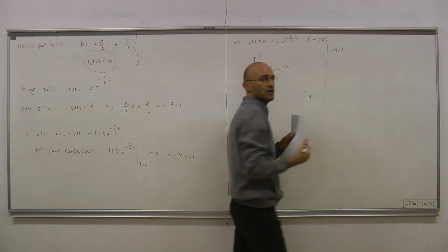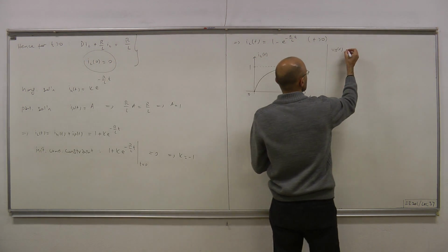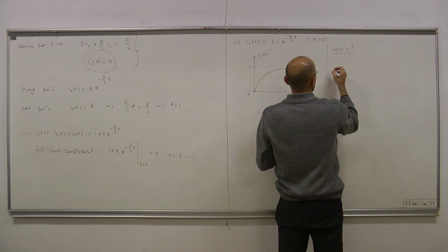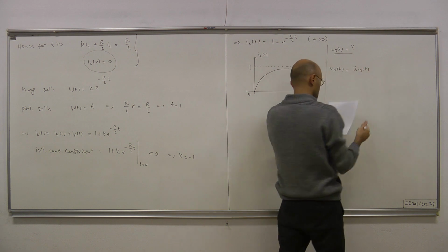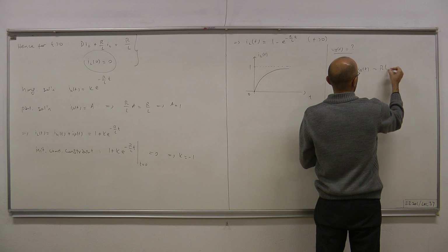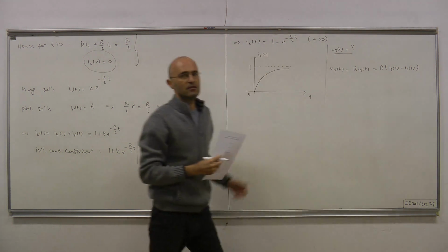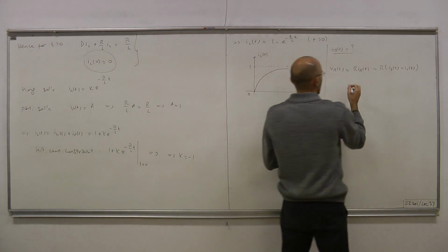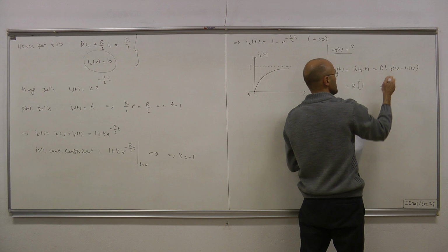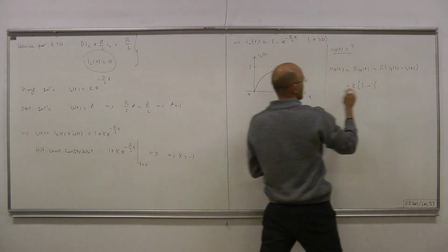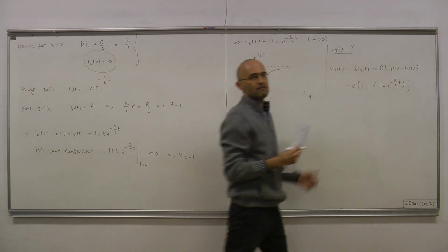Now, next question, which was what we were asked in the first place, is the voltage of the resistor, VR(t). Okay, so let's figure out VR(t). VR(t) is R times IR(t), and by KCL, IR(t) is IS(t) minus IL(t), times R. That equals R times, this is 1 for t positive, minus IL(t), 1 minus e to the minus R over L t.